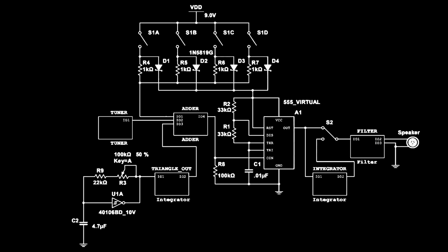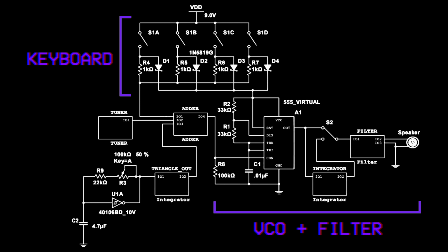This is the circuit that we designed. The keyboard consists of several buttons acting as switches that, when closed, allow power to reach the VCO, as well as powering a voltage divider to provide an input to the VCO. The VCO, built using a 555 timer, can have a frequency range of over 2 octaves. The LFO is designed using a Schmitt trigger and is controlled with a potentiometer.